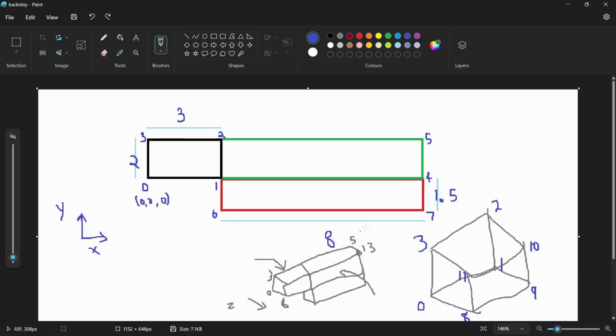Okay, now we will do the outlet, because that is what we want next. If you see, outlet has two faces here, so it is 5, 4 and 7. Now since we know the convention, if this is 5, this is 4, so this will be 13, add 8 to it, this will be 12.